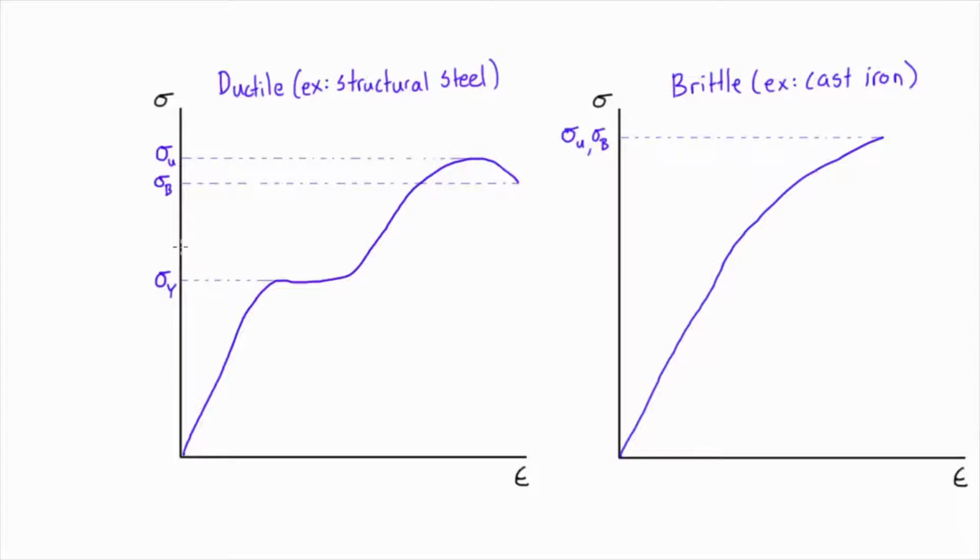These are the internal stresses that are resulting from the strain, which is resulting from the applied load. So the strain in this sense is the independent variable, and the internal stress in the member is the dependent variable, which is fully dependent on how much strain there is. So that's just a huge misconception that a lot of people get wrong when they first see these diagrams, and I hope that I articulated that clearly enough.